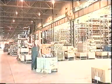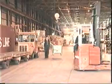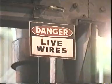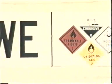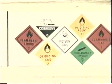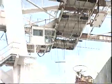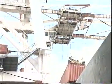Some common site hazards which you need to be aware of include pedestrian and vehicle pathways, clearance from other structures, equipment and electrical conductors, proximity to dangerous materials, and in the case of outside cranes, potential wind forces and adverse weather conditions. The operating plan should also ensure that the work area is well illuminated.